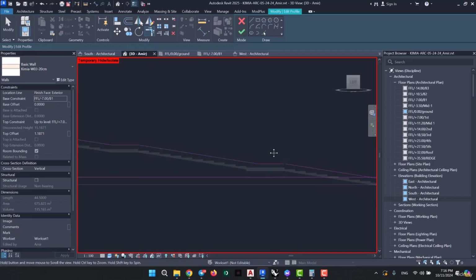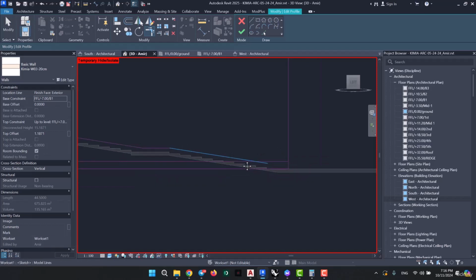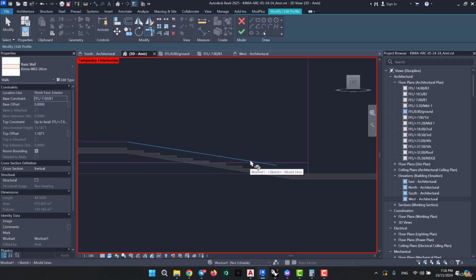And also remember that this only applies for when your client does not require a 100% precise drawing from you. If they expect you to draw a specific form of wall, then you'll have to have a plan and import it in here, and then draw your wall lines according to that plan. Then you'll be sure that it's exactly how they want. But because we had to make some overall modifications to the stairs and we didn't have a specific plan for them, we just decided to draw the side walls for them at a 65 centimeter offset aligned with the slope